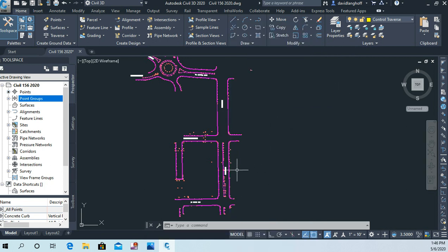We all tied in to a previously surveyed line, and that's how we all got started with our control survey. We had a control point here at the intersection of 6th and Highland, and that was control point 8, and then another control point down here at the intersection of 6th and State, and that was our control point 9. Everybody utilized those two control points.